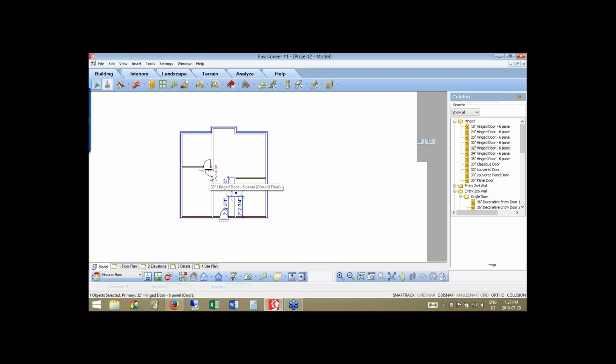This door right here, what if I want it to be all the way down the wall over here to this corner? I can select on those dimensions that appear as well. So I'm going to select on that dimension and tell it that I want it to be 6 inches away from this corner. And it'll move the door all the way down there. And then again, right-click, flip the swing. So once you have doors inserted, you can always move them around and change their position as well. I'm going to make this a little bit bigger on my screen by using my zoom window tool. That's that tool that I'm circling around in the lower right-hand corner of my screen.